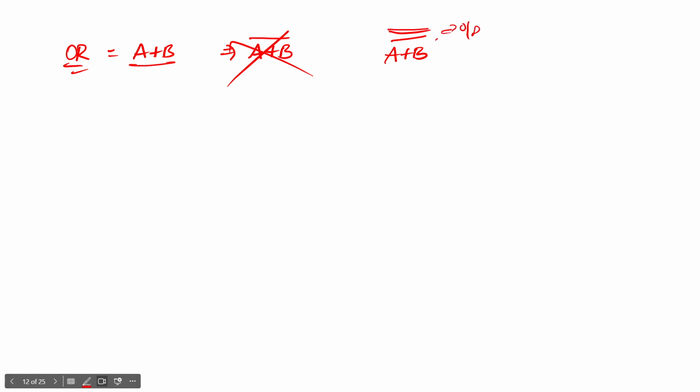So now let's try another thing, without any complement. For example, if I want to design an OR operation, it will be A plus B. If you directly design this A plus B, we get the output as a complement, meaning A plus B bar. So it will be the wrong output. So you have to apply the double complement: one complement for the output and another complement for the equation. So apply the second one inside this complement.